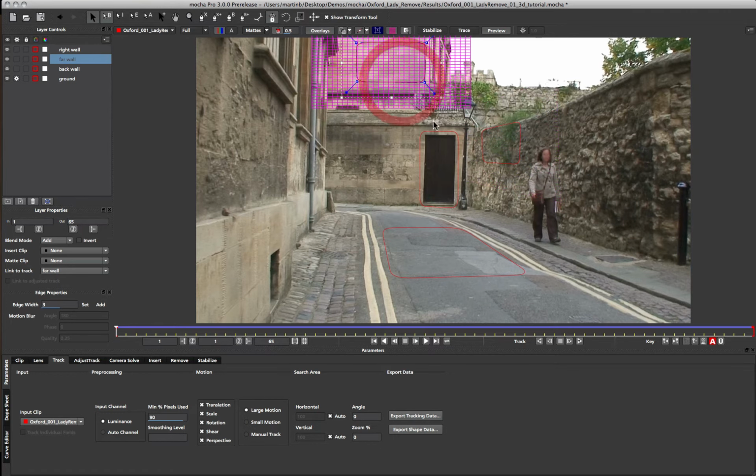I've only chosen to do 4 tracks in this particular shot, just to give me as much information as possible. I could of course have chosen to do more tracks around, just to give myself solid data, like this wall over here, and this wall here, and the front ground here, and even this wall next to the door, but I've chosen to keep it to a minimum. You can add as many planes as you like when you're trying to track, but you want to try and get a good, even amount of different coplanar areas in the shot.